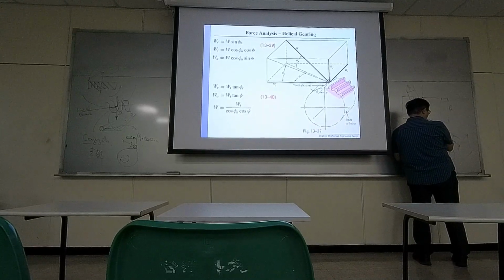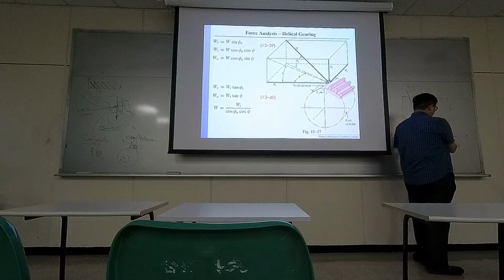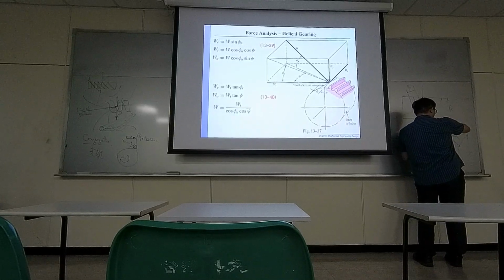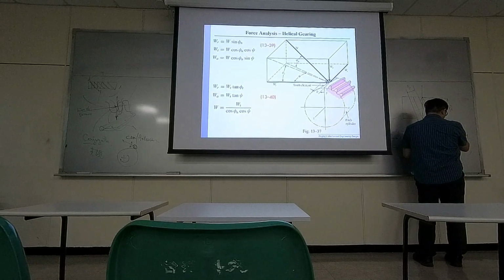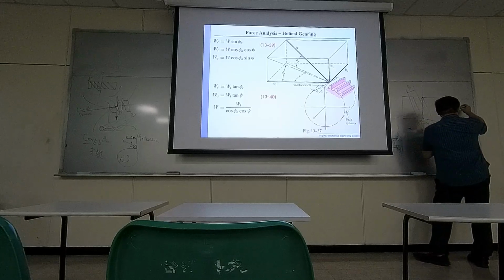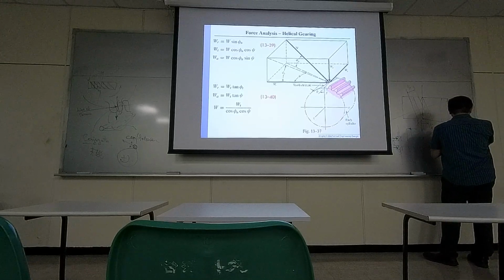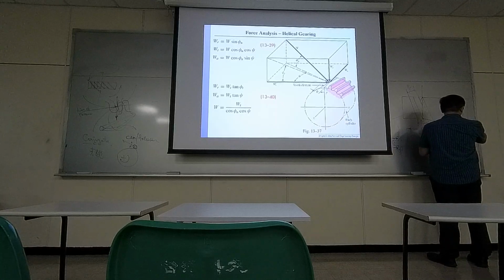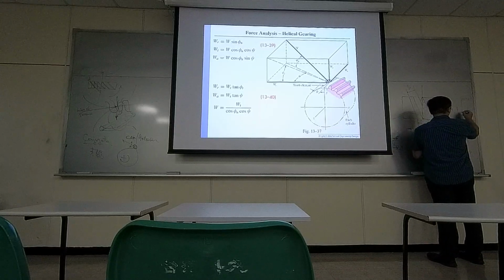Because the pinion, if you are using helical gears, you may have forces driving down, and also the weight of everything. So for the bearing, there will be some forces holding the whole system, and you have reaction forces applied to the bearing. And if you take a deeper look, probably you will have a design like this. So this is the shaft, right?